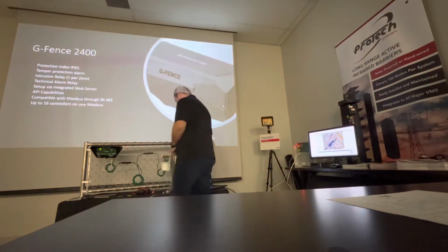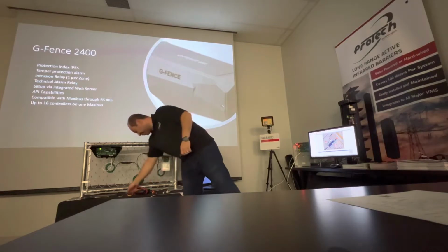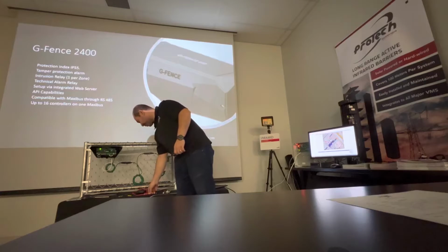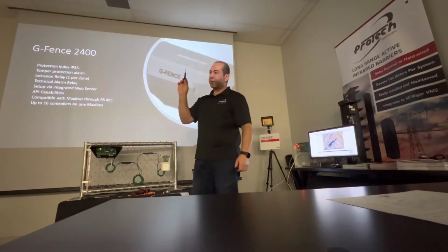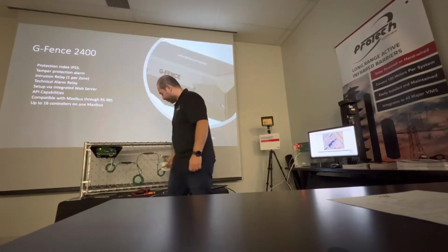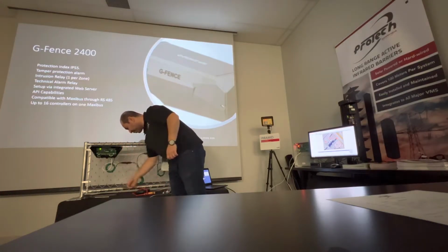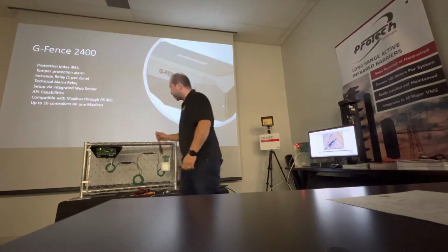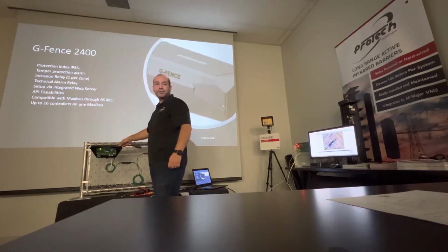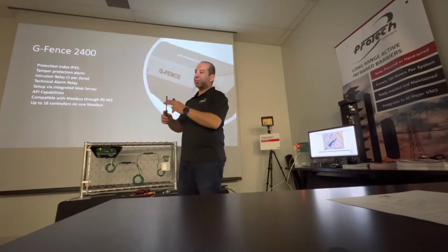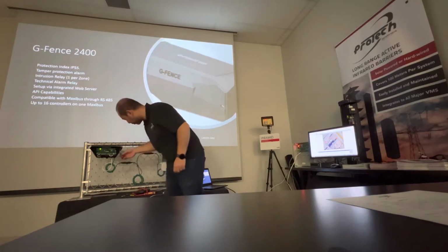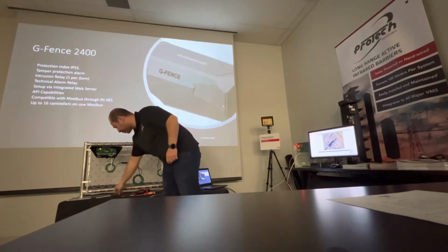So first of all, what we need exactly as tools. You need a screwdriver, a flat screwdriver, just to open the control unit and to work with the terminal block here to pass all your sensor cable. You need a stripper, and if the control unit is outside the building on the fence, there are anchors here. You have to use 8 millimeter nuts, that screwdriver, to be able to twist them.